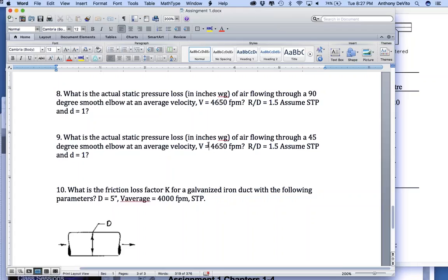So can we generally assume that, at a 45 degree angle, when the angle is half, the loss will be proportional to the angle? Using those charts? Is it really? If you really used fluid mechanics to calculate it, my guess would be it'd be much more complicated than this. But this is good enough for us to use to do an initial design on ductwork.